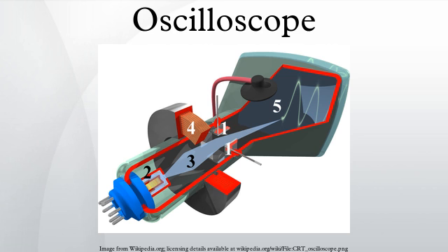Some models of oscilloscope have isolated inputs, where the signal reference level terminals are not connected together. Each input channel can be used to make a floating measurement with an independent signal reference level. Measurements can be made without tying one side of the oscilloscope input to the circuit signal common or ground reference. The isolation available is categorized as shown below.